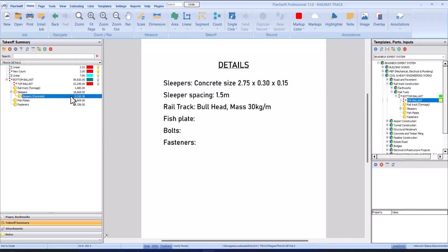If you have timber, depending on the material you are going to extract your sleepers from, you divide and do your pro rata. Also, if it is steel, it depends on the length of the material you are going to use. If it comes in 12 meters or 3 meters, you multiply it with this to get the total meters needed, or total tonnage needed, when you do your pro rata from the number of sleepers, depending on your material.